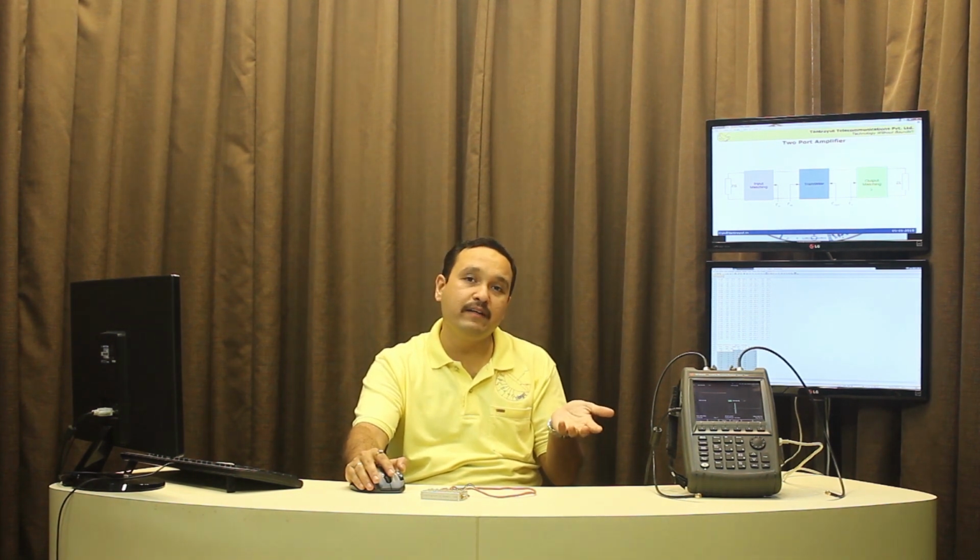What sort of input or output matching network you use depends on your transistor, your frequency range, and how you would like to implement it, in terms of lumped components or distributed components such as transmission lines, microstrip lines, stubs, etc.